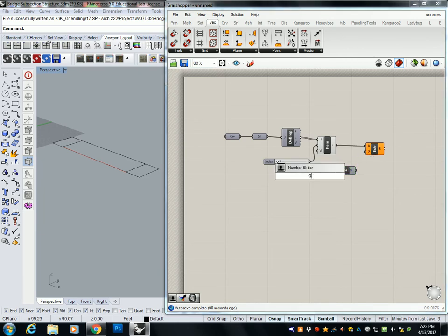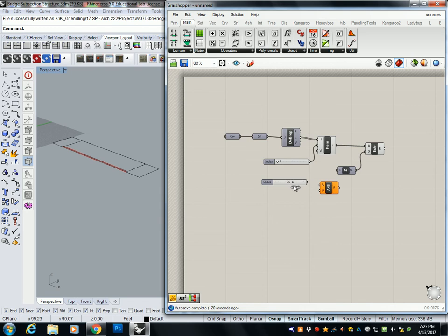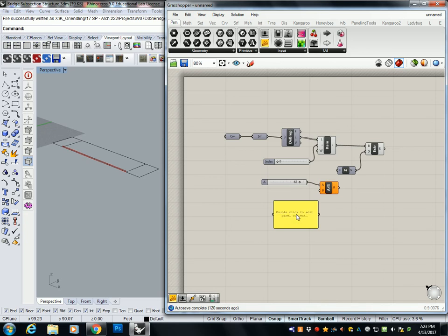and then I'm going to put in my magnitude. Now, handrails and guardrails are very specific to building codes, so they're pretty much based off of inch values. In the interest of being accurate, so that you see a degree of care about that sort of thing, I'm going to transition this into inches. So I'm going to say 0 to 48 at a maximum. And because I want this to convert to inches, but I'm working in feet, I need to divide it by 12. So that's math. I'm going to put this at 42, and I'm going to divide that by 12.